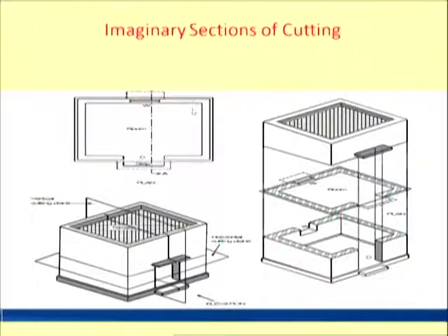So this thickness is a horizontal dimension, it is not the vertical dimension. Similarly, the size of the room: suppose you measure this dimension as 3 centimeters, so you will say the width of the room is 3 meter. Similarly, this length of the room, if you measure with the help of a scale, is 5 centimeter, so it is equal to 5 meter. That is also a horizontal dimension. So the point is that in plan we can only read the horizontal dimensions, not vertical dimensions.